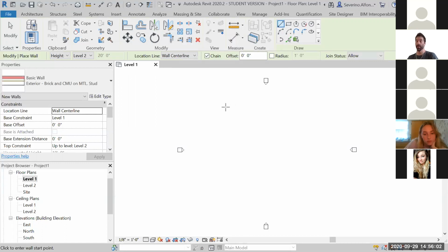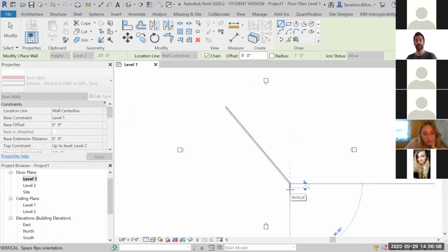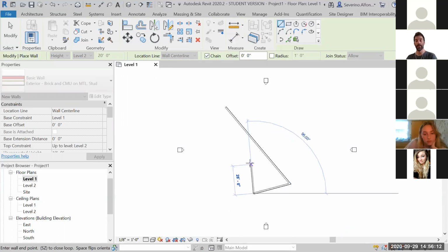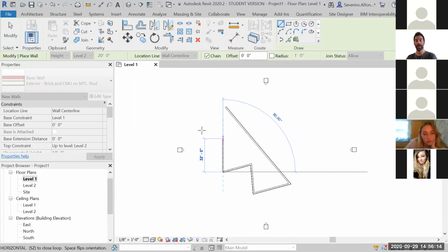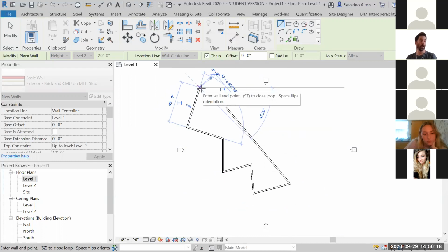The way you introduce a wall is by clicking once, obviously, and twice, two clicks. You can continue the wall if you keep on clicking. That means that you're actually generating a continuous wall that has the shape of a polyline. Only when you're done, you can escape once.